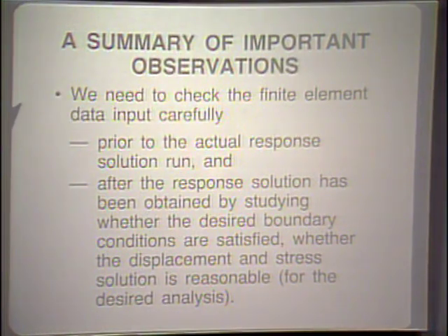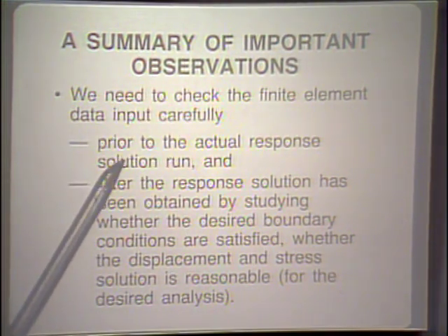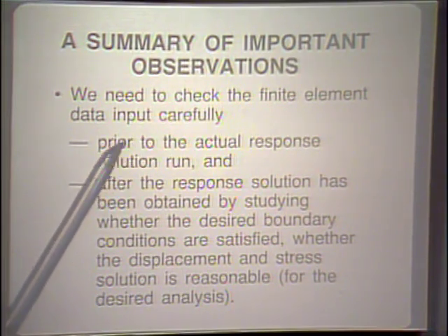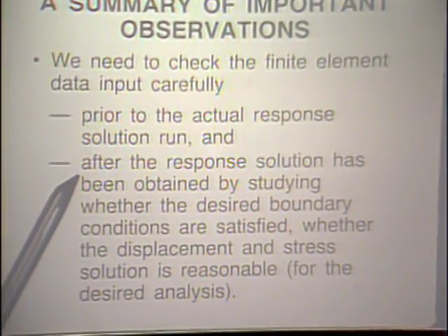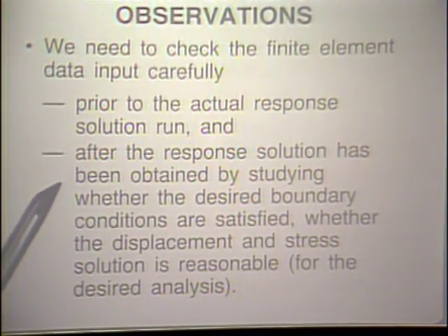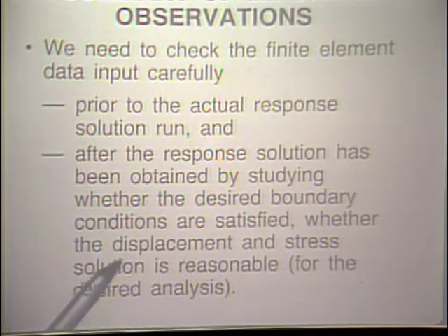With the analysis now completed, I'd like to look with you once more back onto 2 view graphs that we already have looked at earlier. We, on these view graphs, summarized some important observations. And we said that it is very important to check the finite element data input carefully prior to the actual response solution run. That, of course, means plotting the data, and we have done so in our analysis. And after the response solution has been obtained, by studying whether the desired boundary conditions are satisfied, whether the displacement and stress solution is reasonable.